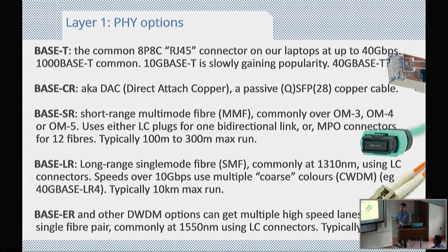Jason, high density connectors, the MPO. Are there single mode equivalents to that? Yep, you can actually get MPO with single mode fibers in them, and there are some guys who do that to break them out, but it's not very common. There's a 2-kilometer silicon photonics standard that uses that scheme. I think I've got a slide on this a bit later.